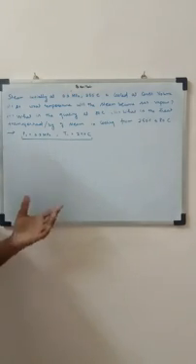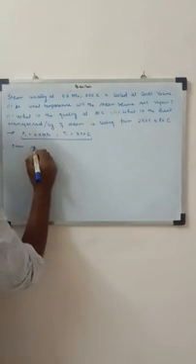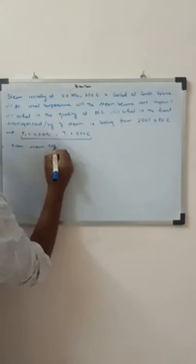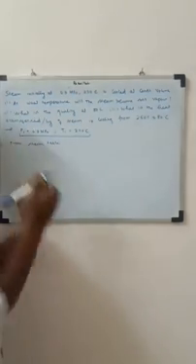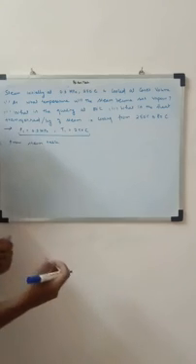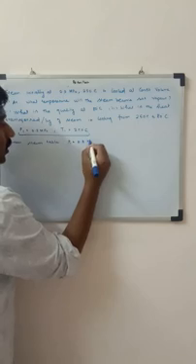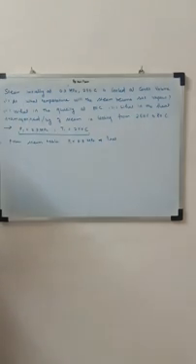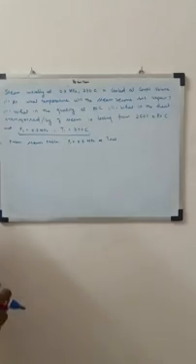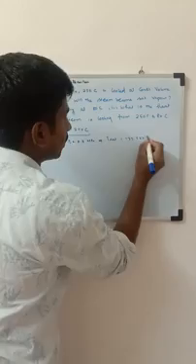So what do we do for that? Let's go to the steam table. From the steam table, let's see what is the saturation temperature for this particular pressure. When the pressure is this value, at what temperature will it change phase? For P1 equal to 0.3 megapascal, the saturation temperature is 133.522 degrees.